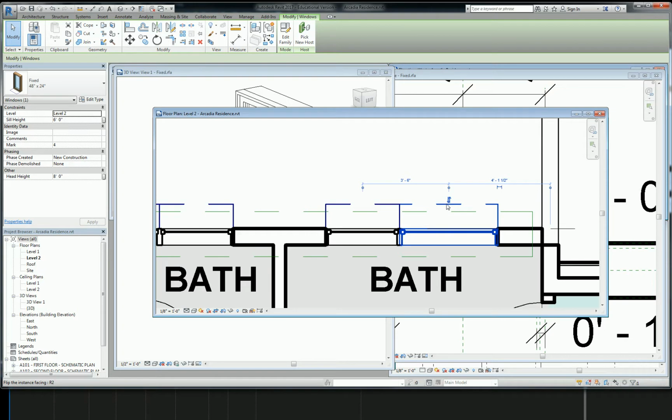Shouldn't it be just for the one side of it, not 2 sides? Yes, we're going to do that in the next video, where I'll show you how to. Because we make it like one window, and it was not 2 different windows. It was just one. Yeah. So that's why they show up with both of them, right? Exactly. Yeah. So we modified the window type, and we need to add a parameter that's going to say whether or not we want this window to have it, without making a new window type. Does that make sense? Yes. Or window family, I should say, not the type.